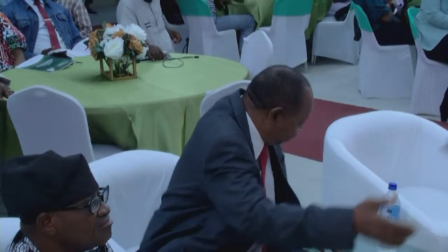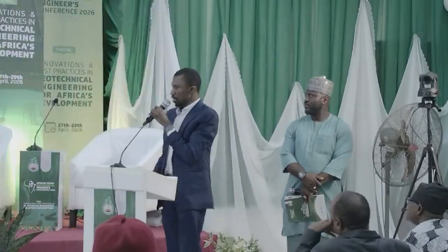Thank you so much. Okay, so for the first question, the soils were collected in Brazil by digging through the soil. Within the first 2 meters is lateritic soil. Then below that we have saprolitic soil. They actually have little differences. From the literature itself, in the lateritic soil, the predominant minerals are hematite, gibbsite or so. But when going down, we have soil that contains more fines, based on what was reported in the literature I used for this.